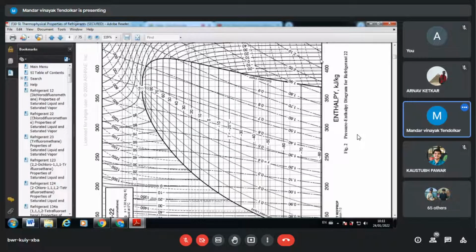This is a kind of modified version of the conventional chart. The conventional means PV chart. You know PV very well. You know TS very well, temperature entropy. But my job is to find out enthalpy, neither volume or pressure or temperature or anything. Rather, the intersection of that pressure, temperature, whatever it is. The final objective is to find out enthalpy. Do you agree? Because we have to find out H2 minus H1 and H1 minus H4. So the basic job, final aim is to find out the enthalpy.